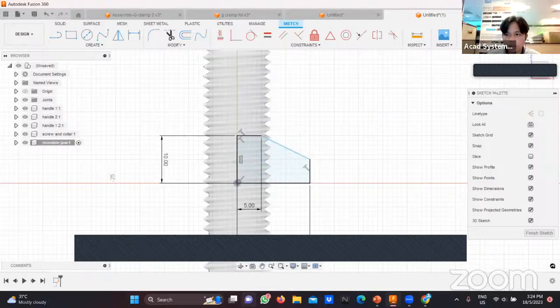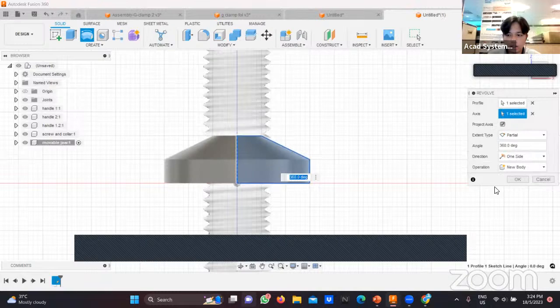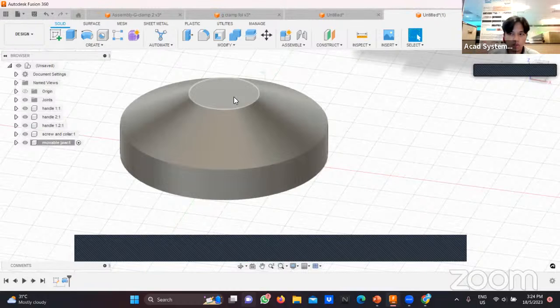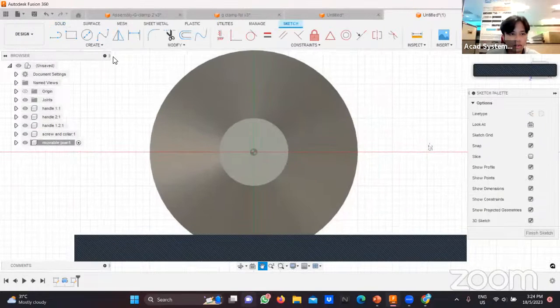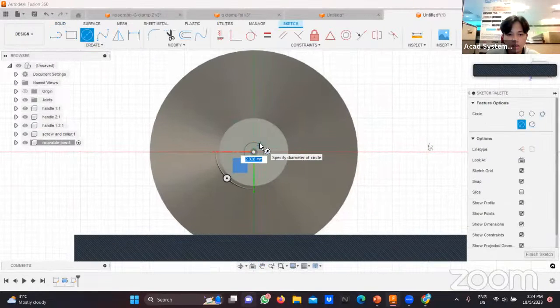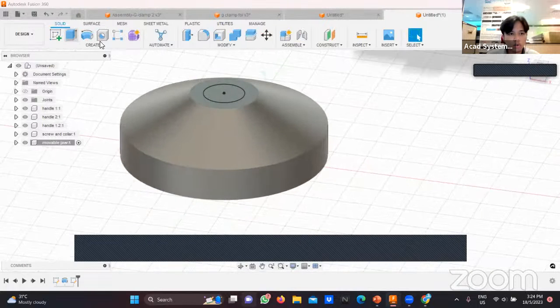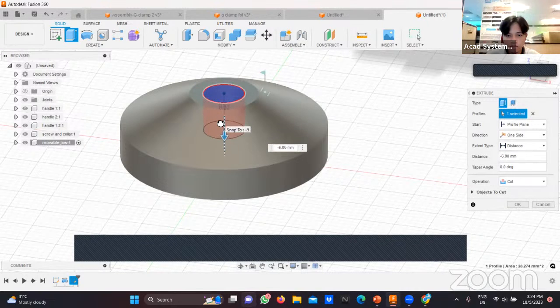All right, go finish sketch, select revolve, select the axis, press OK. Now to create a hole here, you can just create sketch. Put it in the middle, in center, 6mm, enter. And then for finish sketch, go to extrude, select the profile, -6mm, and then press OK.